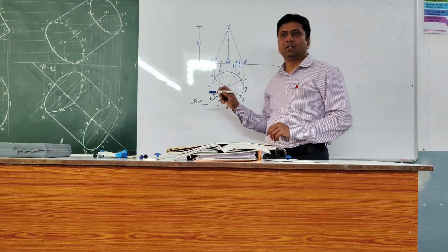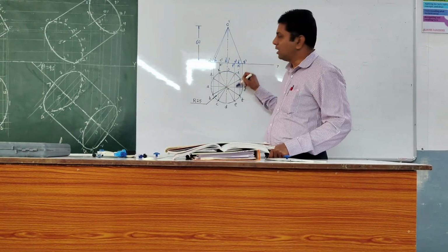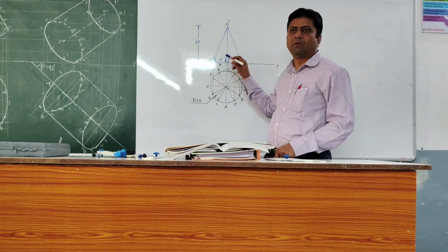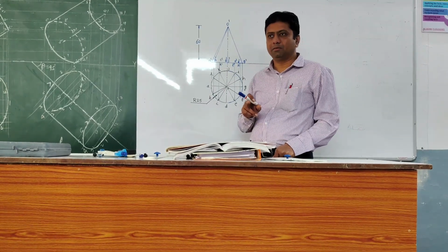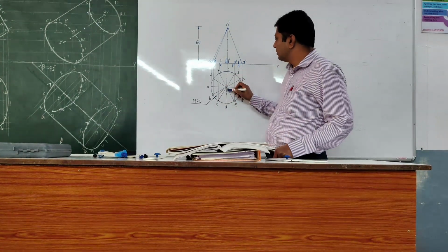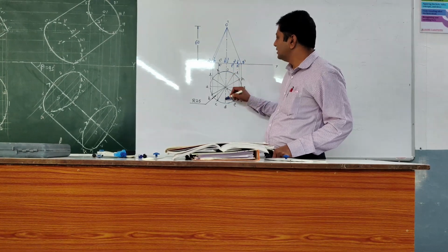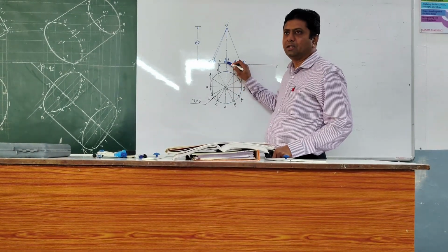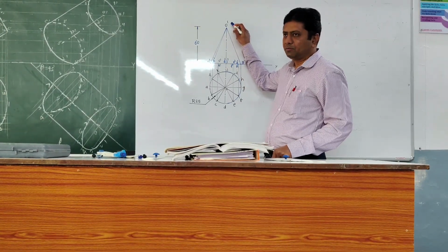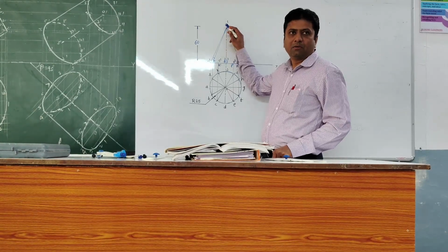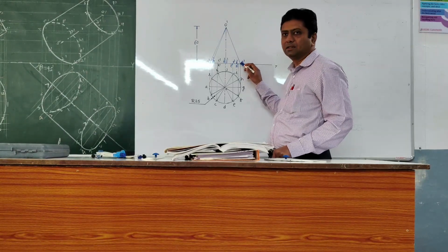Next step, take the projection of each and every point vertically upwards up to the reference axis X1. Now the axis height is given in our question. What is the axis height? 60 mm. So the center is O. Here you can find the projections D dash, J, J dash. From the center, take 60 mm and mark the point O dash. That is your apex of the cone. The front view, as we know, is a triangle. So join O dash, A dash, and O dash, G dash.